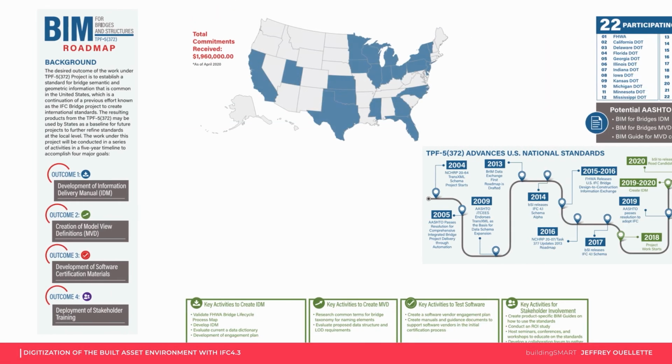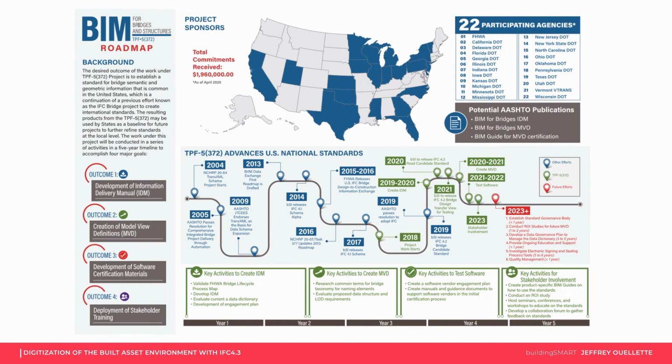I'd like to highlight one significant component of that larger effort. It is a project with financial backing of almost half the transportation departments in the US. This is to create BIM-based standards for the design, delivery, and operation of bridges and related structures, specifying the use of IFC 4.3, as well as using BCF and the buildingSMART Data Dictionary. Today it is bridges, but soon there will be projects for roads and other infrastructure by the American Association of State Highway and Transportation Officials, also known as AASHTO, creating standards which will be used across the entire US.